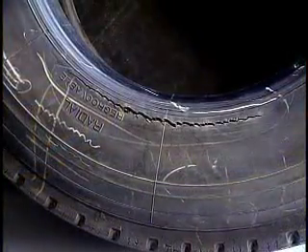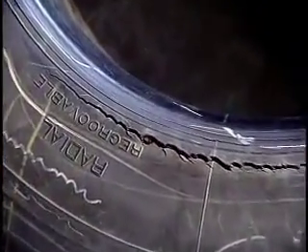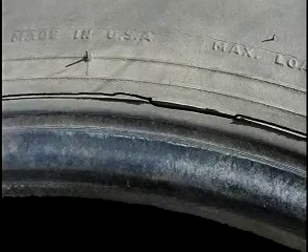Pinch shock conditions are often confused with guide rib or chafer separations. The way to distinguish between the two conditions is that pinch shock tends to be a localized damage, often accompanied by abrasions and cuts in the sidewall. Chafer separations tend to be more circumferential in nature and are associated with casing fatigue.